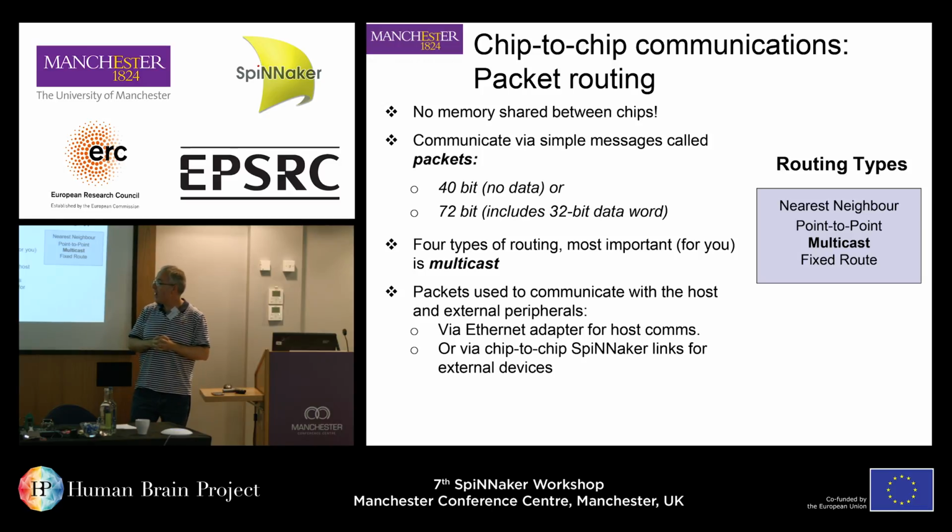There are 2 main ways of getting information on and off. As I said, one is the chip-to-chip links, that SpiNNaker has 6 links, but also every board has an Ethernet connection which you'll be using to connect to your host. That is used both to download the information at the beginning of simulation and also to read off the results at the end of simulation.